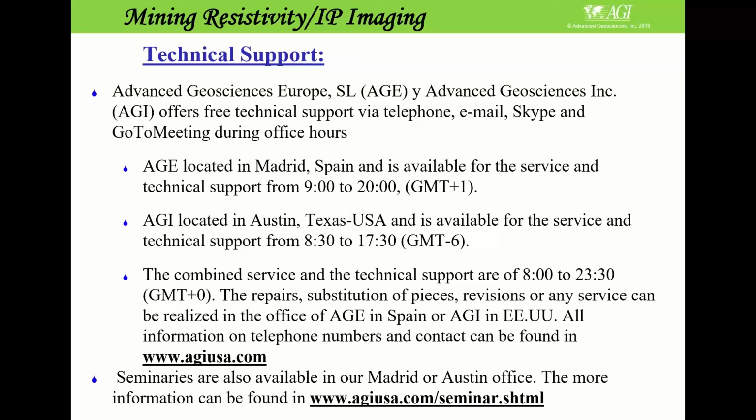So I see this morning somebody asked a question regarding coal mining and what resistivity IP studies can be done. Well, I should say that not only coal, but all studies have to be evaluated separately, because you need to know the geological lithological structure in the area. And I know in some areas the coal investigation is a repeating of lots of sediments: clay, silt, sand, and then lignite in the area.